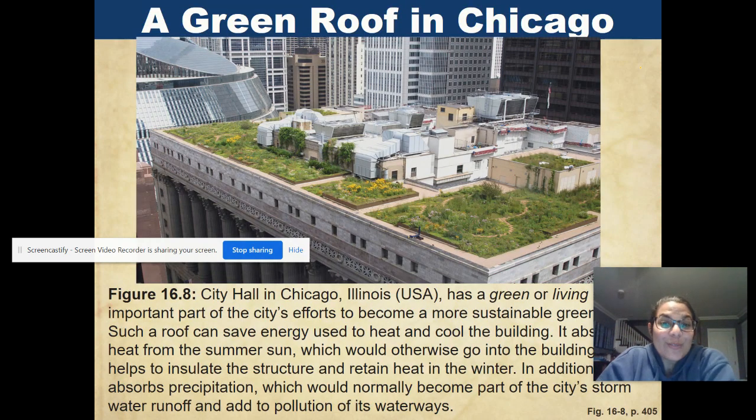Okay. Green roofs. These are like my favorite things. And you can't just stick a garden on top of a roof. Like none of you can put a garden on top of your house. Buildings have to be retrofitted to actually have these green roofs. What you need is a huge drainage system. Water weighs a lot, dirt weighs a lot. And so a lot of the older buildings have to be retrofit to have these green roofs.